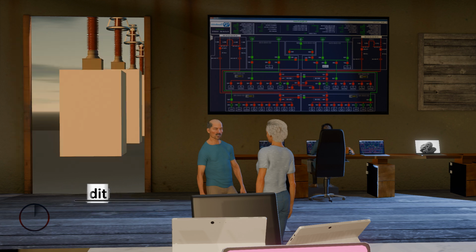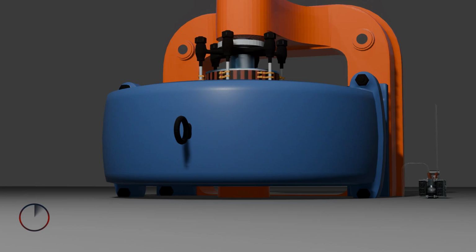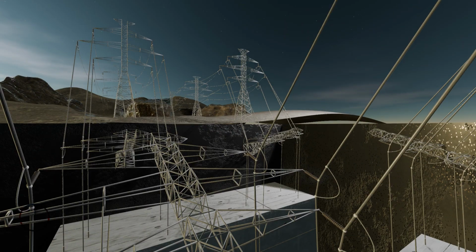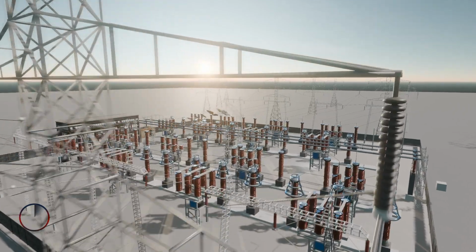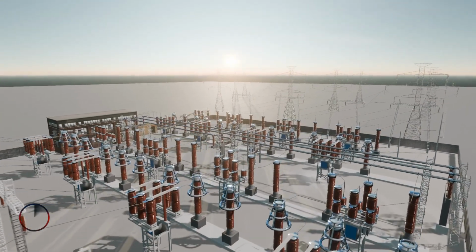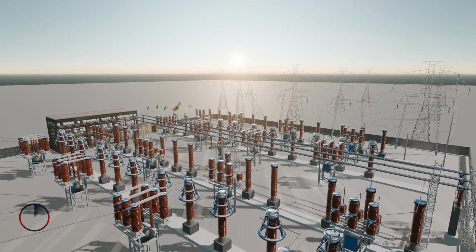So in layman's terms, the voltage of the generator must be the same as the voltage of the network. That is, if the network voltage is 190 kV, then the generator voltage must be 190 kV before synchronization can be safely done. Also, the frequency must be the same.